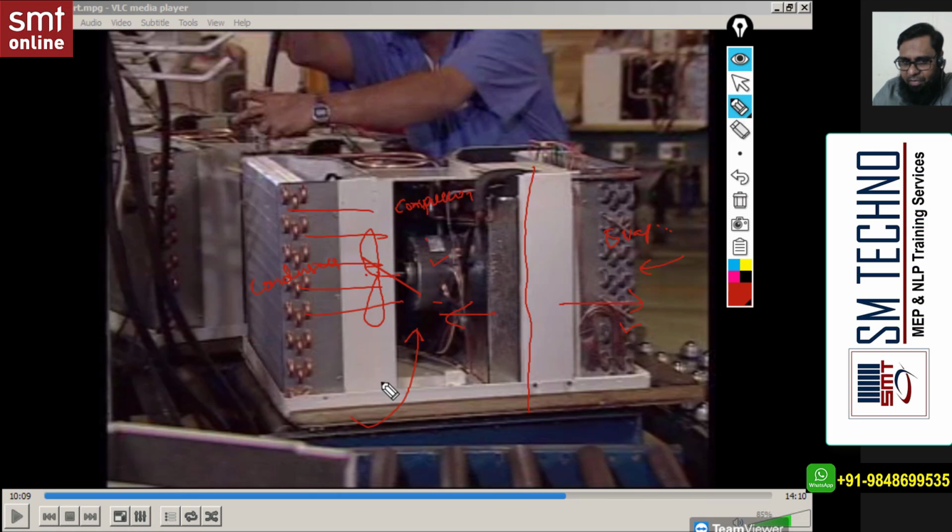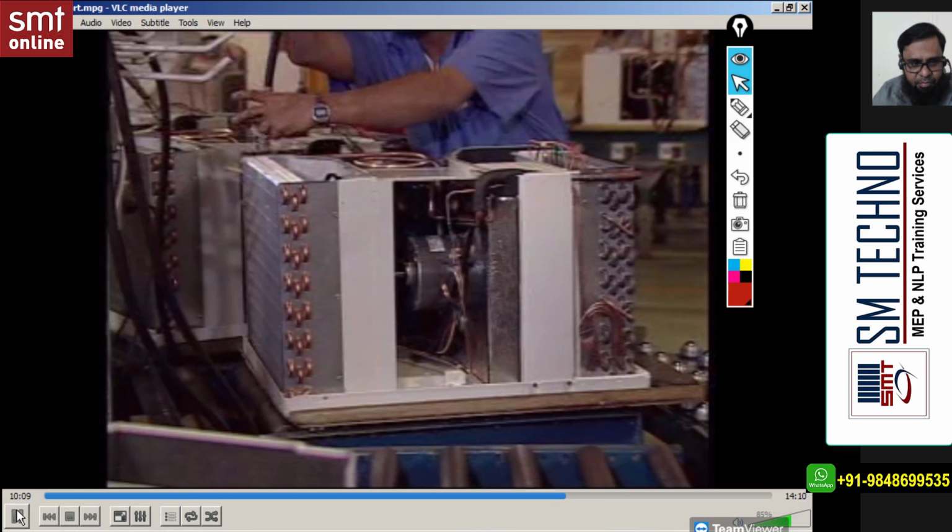After that liquid state, through this expansion device, we'll get the cool refrigerant with low temperature and pressure flowing into the evaporator. When the air sucked from the room passes through this evaporator, it loses heat and moisture. So at the other side you'll get cool and dry air, meaning cooling and dehumidification, the same concept.